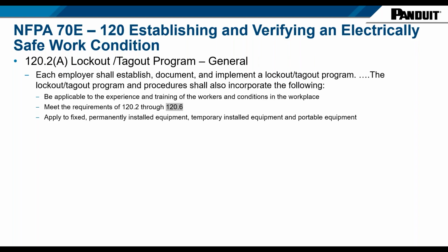But you can reference any of this content online for free, which is a good thing to mention. But the lockout tagout program, again, needs to be applicable to the experience and training of the workers and conditions in the workplace. So again, tailored to your needs, and it needs to meet those requirements that are defined in the standards. And then it has to apply to fixed, permanently installed, temporarily installed equipment and portable equipment. So pretty much any electrical equipment that you've got that causes a hazard.